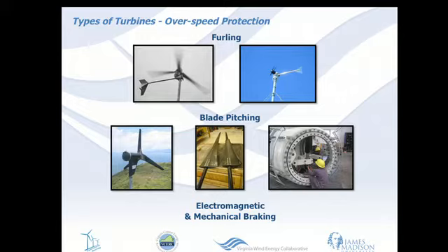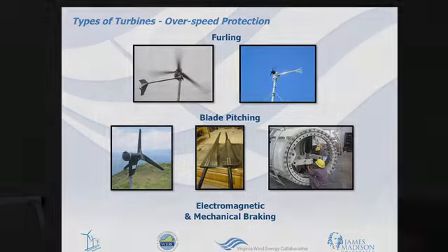So horizontal furling is where the blade essentially kind of folds to the right and causes the rotor to rotate out of the wind, keeping it from catching it at a proper angle, basically stopping it from spinning effectively. And vertical is essentially the opposite. Instead of rotating to the side, it will rotate and fall back like that. I haven't seen too many vertical designs before.